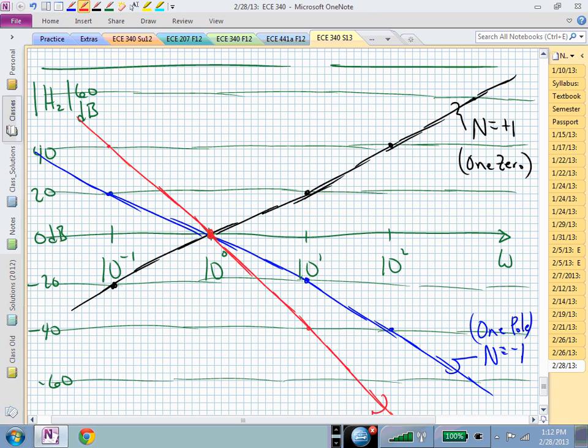Infinity, isn't it? We don't really have a bounded gain. It's infinite when we have a pole at the origin, and that's what this is telling us. And that's maybe what you want to get rid of certain kinds of behavior in a circuit. You might want really high gains at low frequency. And that pole at the origin is going to allow you to accomplish that. Is that clear?